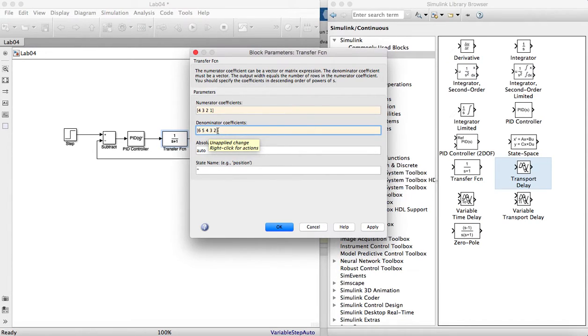But similar to our PID controller, it is desirable to simplify our transfer function in terms of variables. Because we know that the first order plus dead time transfer function is something like G(s) equal to K divided by (tau s plus 1), multiplied by e^(-theta s), which defines the dead time.